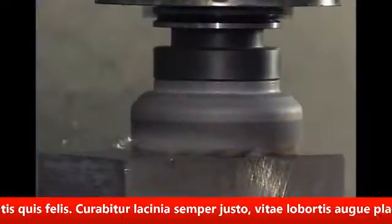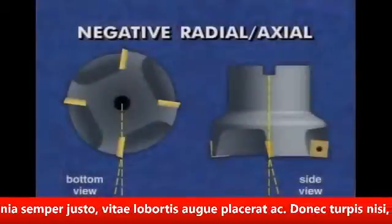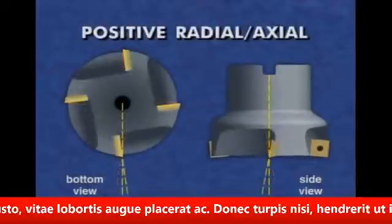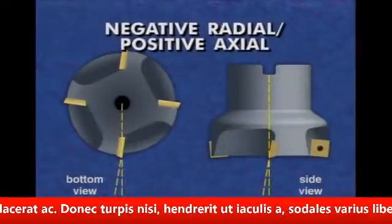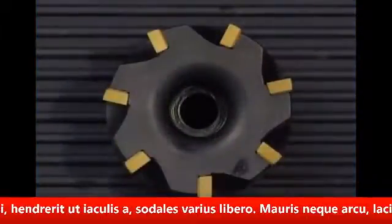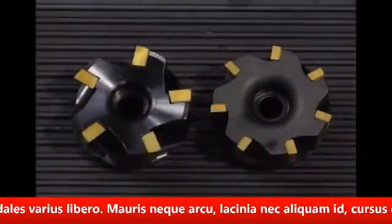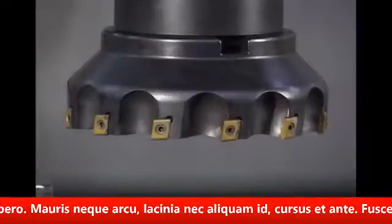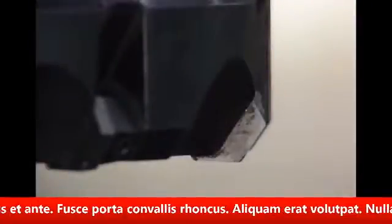These two may combine in three ways for three different geometries of face mills: negative radial and axial, positive radial and axial, and negative radial, positive axial. Face mills may be coarse pitch, fine pitch, or extra fine pitch, depending on the number of inserts relative to the tool's diameter. The coarser the pitch, the larger the gullet size. Milling inserts with a large corner radius or a wiper flat provide a fine surface finish.